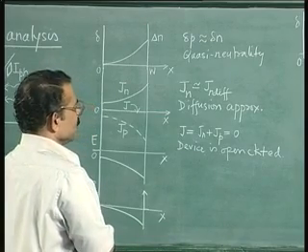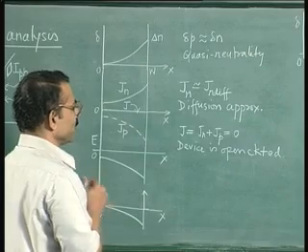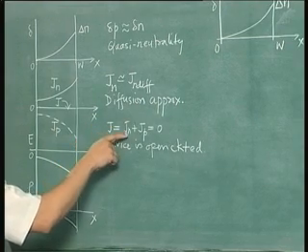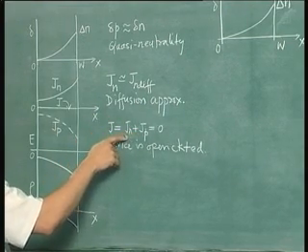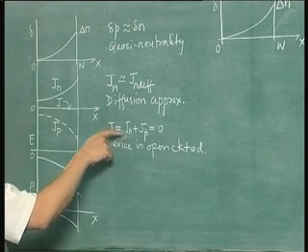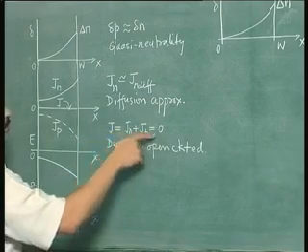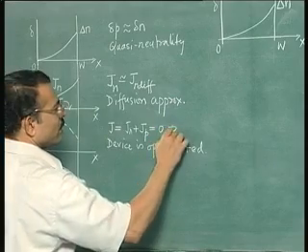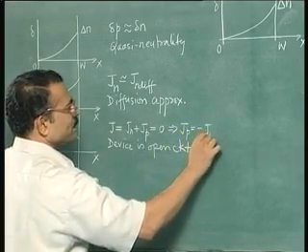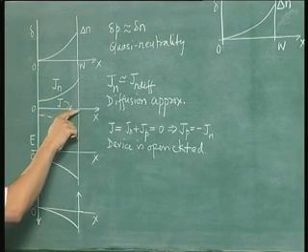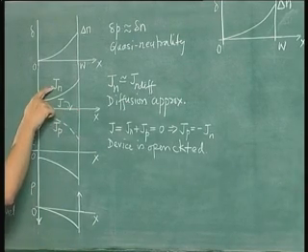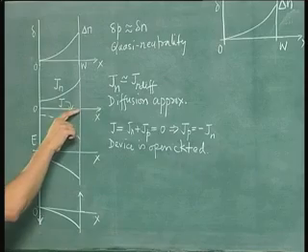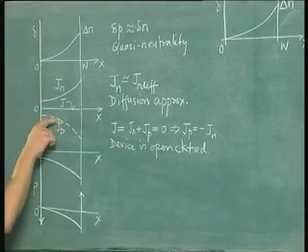You should see the consequence of steady state that we have discussed earlier. So dJ by dx is 0. So the total current in the device due to electrons and holes, we are not talking of individual currents, is constant. Whatever is the value at the terminal, the same is the value inside the bulk, so it is equal to 0. Since this is true, you get Jp is minus of Jn, simply minus of Jn. This is what is plotted here. J is shown to be 0 throughout and Jp is the negative of Jn. So this is a curve that is similar to this but reflected onto this particular surface. So this is a reflection of this.